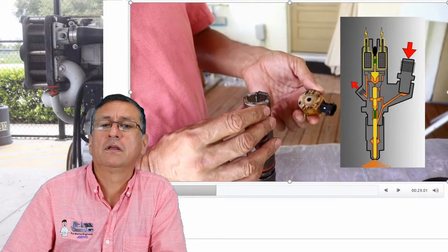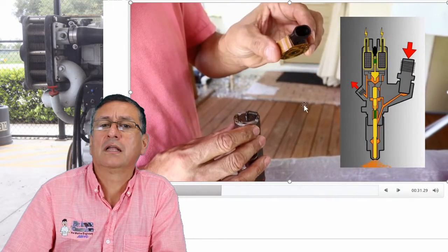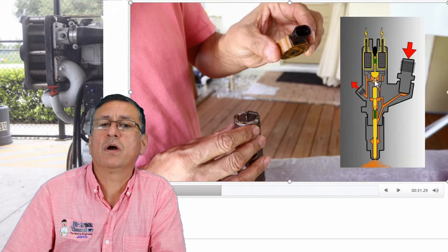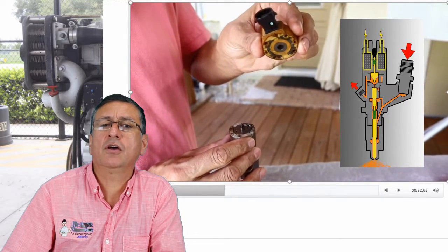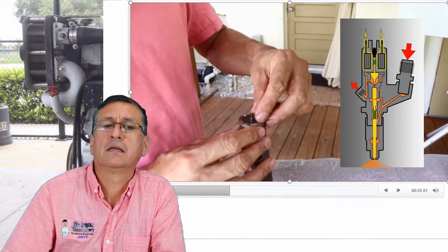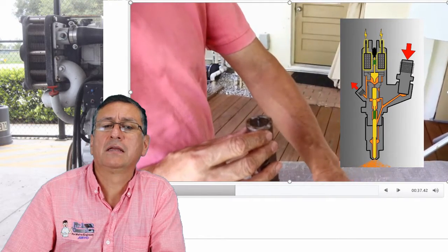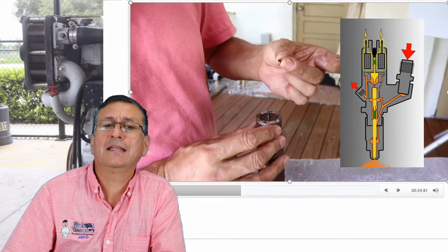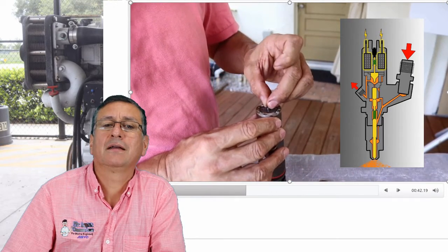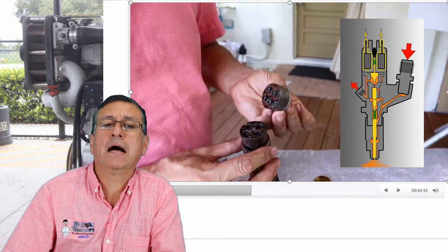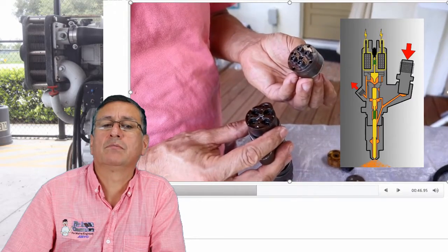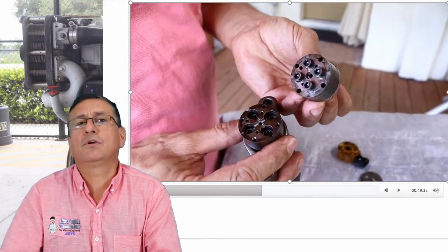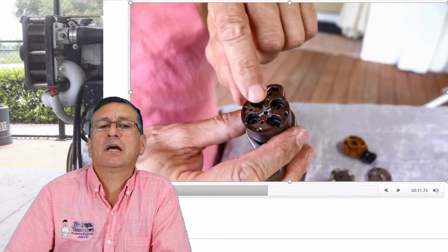We are going to remove the solenoid. The solenoid is here, is located over there, and this is the pin, and this is the washer and the pin. Let me show to you the solenoid, exactly, this is the spring, and this is the washer. Perfect. And this is the body of valves. Simple, simple. That's the procedure to disassemble the injector.